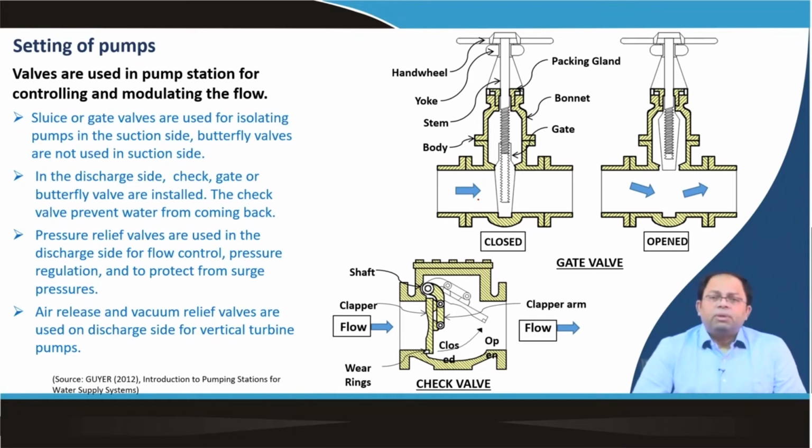And usually we have not one pump, but multiple pumps. Sometimes one pump is run, sometimes another pump is run. So it's not every time that all the pumps are in operation, but all these pumps are usually connected to the same pipeline, and that is why whenever one pump is stopped, there would always be a tendency of water to come back into the pump.